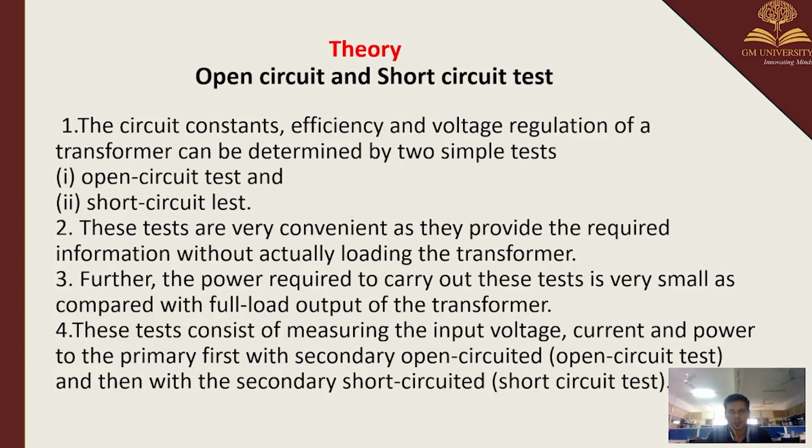These tests are very convenient because they can be done without actually loading the transformer. Further, the power required is very less as compared with the full load output of the transformer. This test consists of measuring the input voltage, current, and power to the primary, first with the secondary open circuited, then with the secondary short circuited.